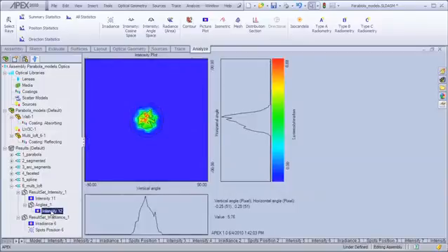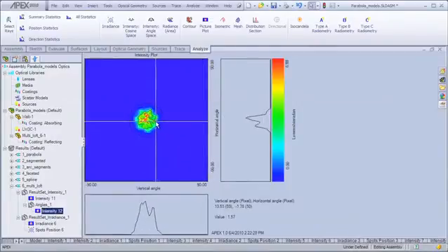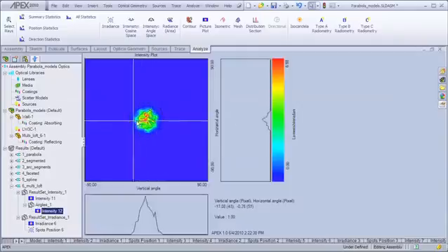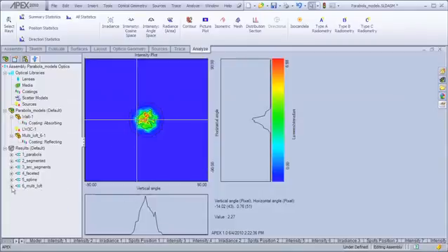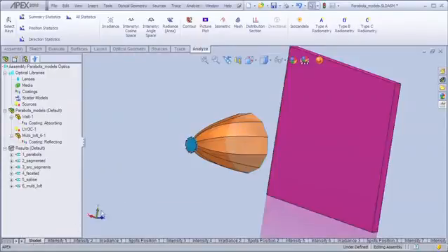And again, we'll end up by looking at our angular spread. And in this case, we do have a reasonably wide set of angles, so we're not truly collimating our light. In this case, in the range of about plus or minus 12 to 13 degrees. But again, for some floodlight type applications, that's exactly what you want. So what we've looked at are several different examples of how to start with a base parabolic reflector and how to modify that shape to try to get what is best for your application.